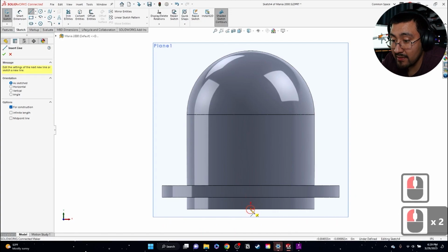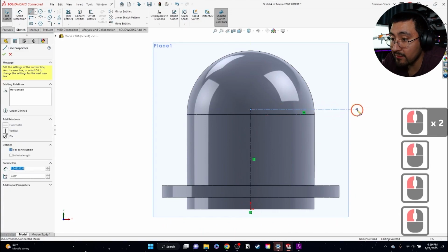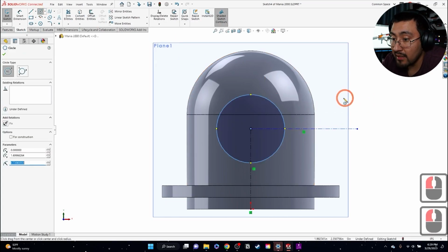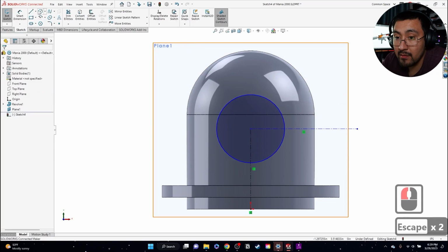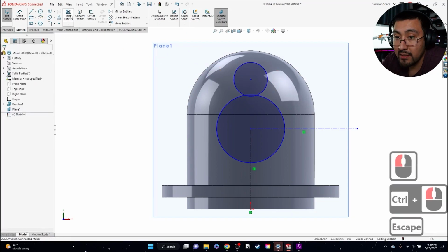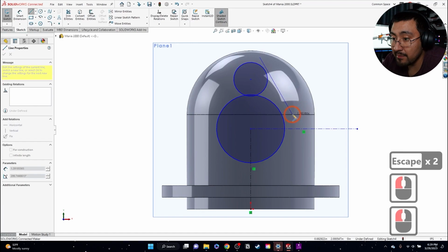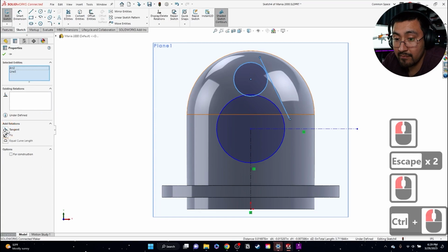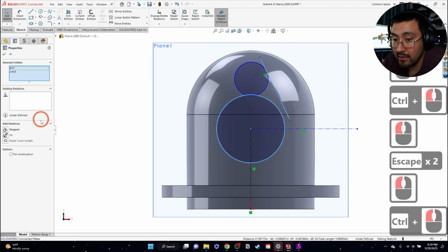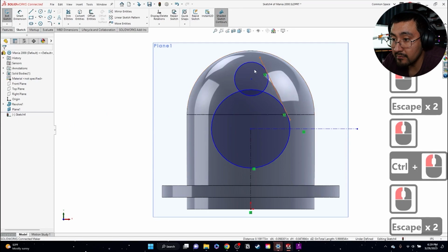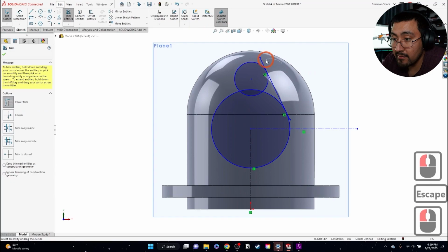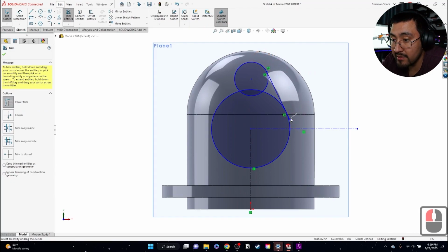I'm gonna grab a center line here, and then I'll make one to the right. And I'll describe why I did this in a moment. I'm just gonna blow that circle up. I'm gonna put another circle here. Actually, before I do that, I'm gonna do one more thing. I'm gonna put a line here and make this tangent here and tangent here. I could easily do this with trim. So I'm gonna trim this edge off, and then trim this edge off.